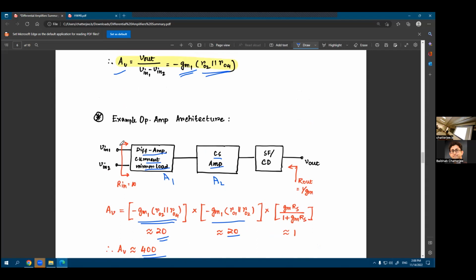You can satisfy the criteria that your input impedance is infinite because you are only seeing the gates of the devices, and ideally there should not be any current flow into the gate if we are looking at low frequencies, right? So we solved one homework problem where your input impedance was not infinite. So homework 6, where we are looking at the parasitic capacitances and we are thinking about high frequencies. So at high frequencies, the assumption that your input impedance is infinite will not hold true.